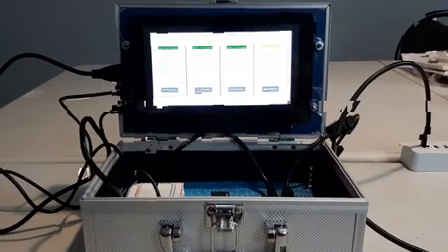I can turn on and off the module for each room. So 4 rooms are shown here. For each room we can separately have these buttons. We can select whether that room works in heating or cooling mode. This is cooling or heating mode. So it depends, and it changes the direction of the rotation of the damper.